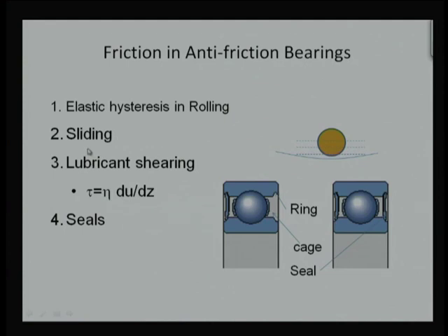We know very well the lubricant is going to reduce the friction between two surfaces, and the lubricant itself is going to cause friction. Naturally, it needs to be a combination. That's why we consider lubricant and sliding, or lubricant and velocity components separately, load dependent components separately, and seal dependent components separately.